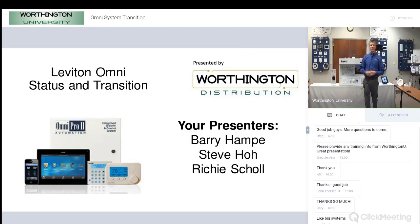If the big system comment pertains to the Fibaro, with a single Fibaro system, if you're within like 5,000 square feet and 150 Z-Wave devices, you're good. If you go beyond that, we're going to recommend that you engage the remote gateway feature, break it up into 2 or 3 systems and bring it all together with the Home Center 2.